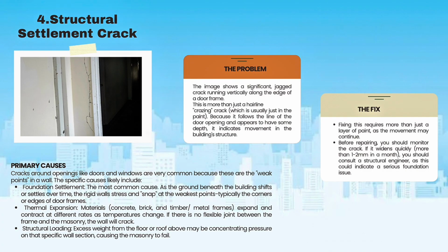For 4, structural settlement crack. The problem is the image shows a significant crack running vertically along the edge of a door frame. This is more than just a hairline crazing crack because it follows the line of the door opening and appears to have some depth.